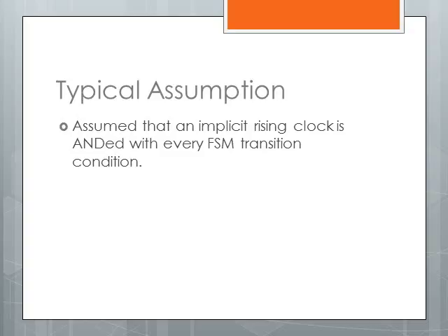Unless otherwise stated, each transition, so each state change, happens on the rising edge of a clock, which means that once you boot up and start at your initial state, your state machine will continuously go until there's no more clock signal or no more power.